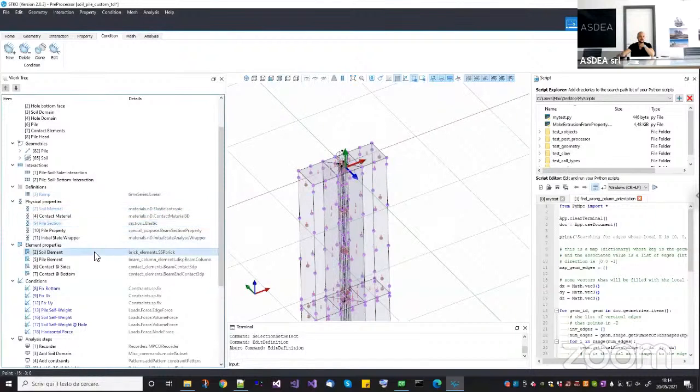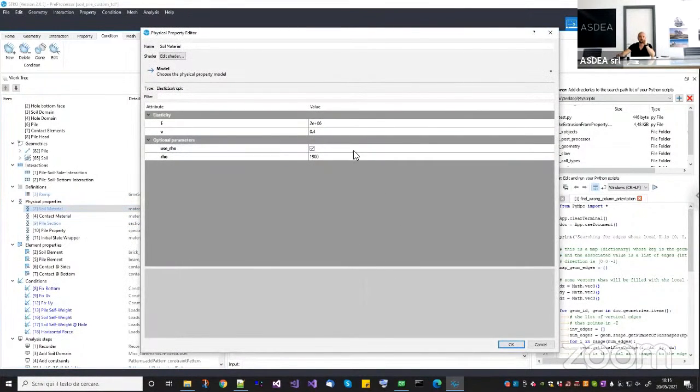But as you can see, I didn't use an elastic beam column because in this way, for example, if you want to test a nonlinear beam or a beam with fiber section, you just go here, you change the elastic section into a fiber cross section, and you're ready to go. So the elastic soil was an elastic line, in Newton meters. And actually here I added the mass density, but it is not important because we are going to do static analysis.